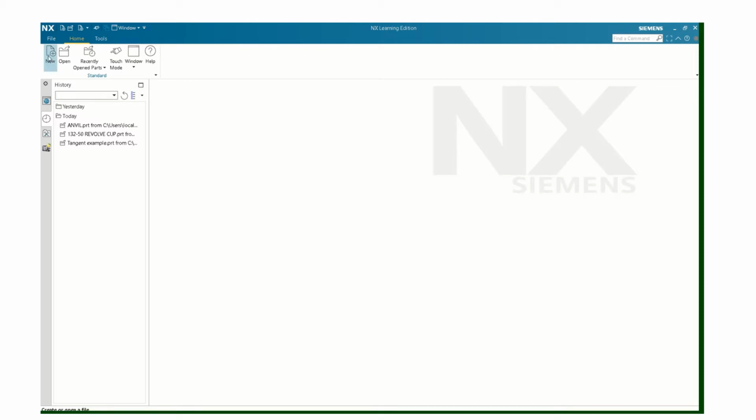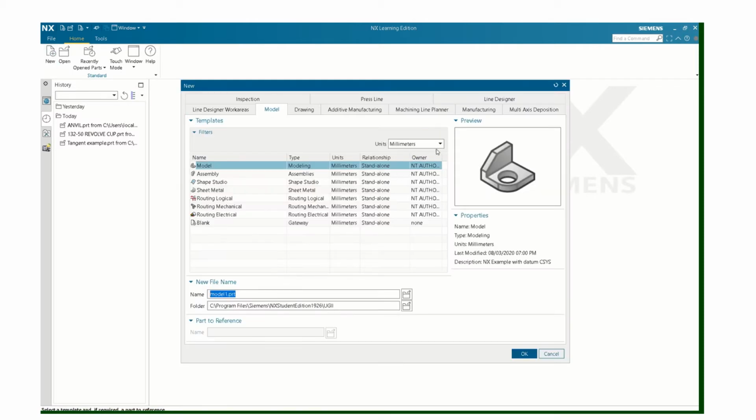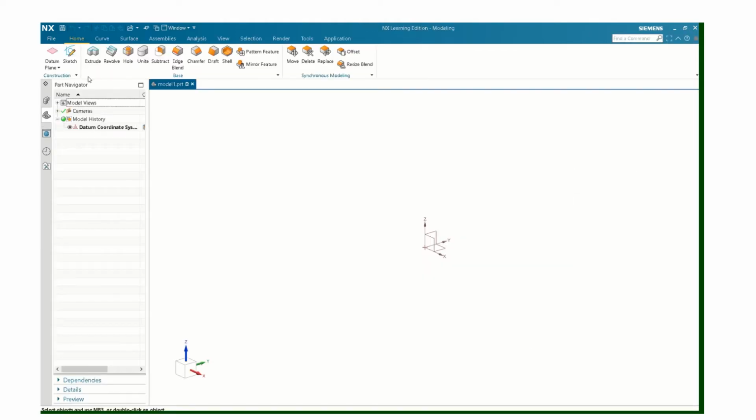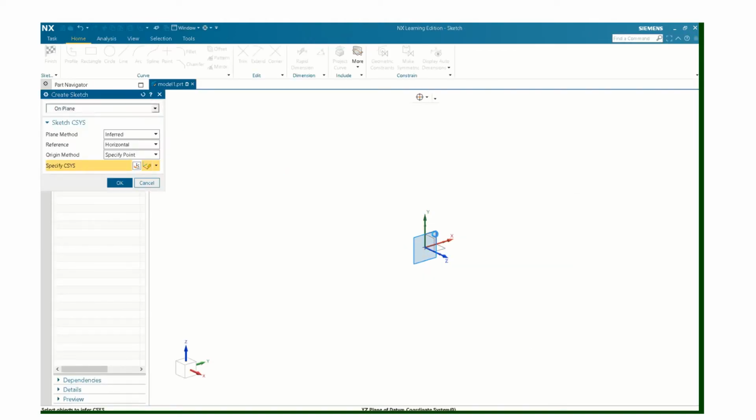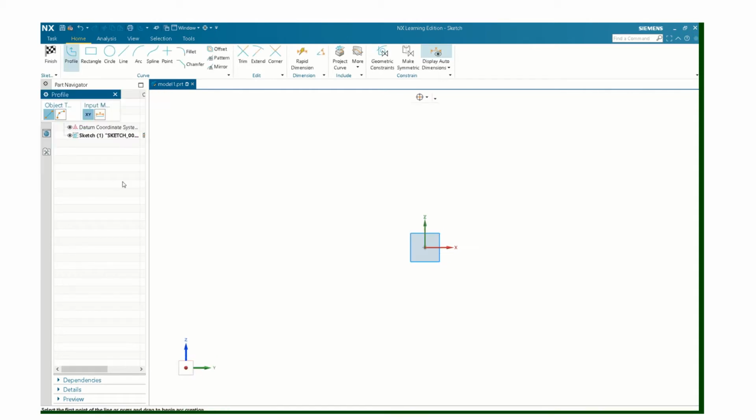In this video, I'll show you how to construct a part using the Revolve tool. And this part's in inches. Start a sketch, choose a plane. I'll use my profile tool. Now this part's going to have a hole through the middle vertically, so I'm going to offset it from the origin. Don't worry too much about where it is in relation to the origin. We can put a dimension on that as we go.